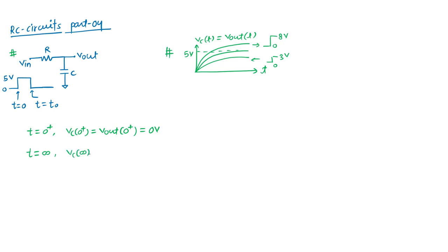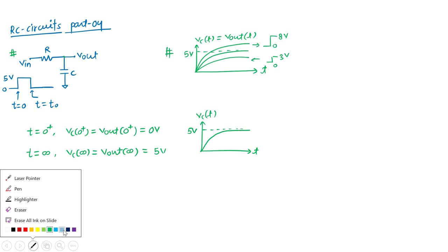So at t equal to infinity, we have seen the two states always. Vout at infinity, I'm considering the capacitor is open at that point because DC is already there; this 5 volt has been set for a long time. So I'll say it is nothing but 5 volt. Again, it should be some sort of 0 to 5 volt at infinity. But what is happening? Let's say t naught is some instant, and we will define the value of t naught.